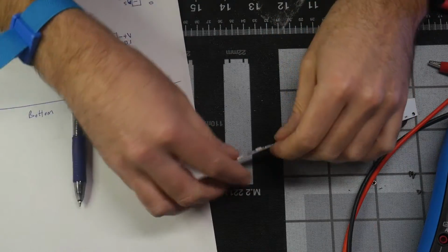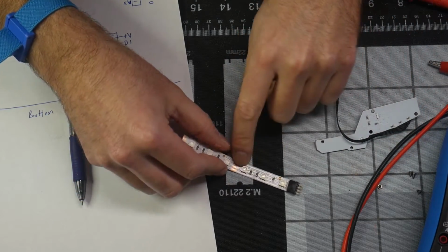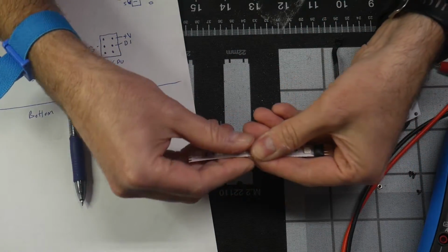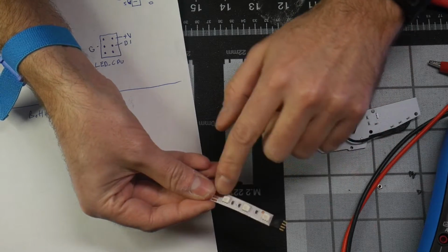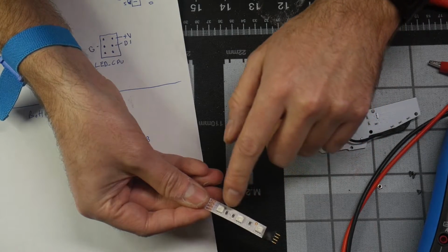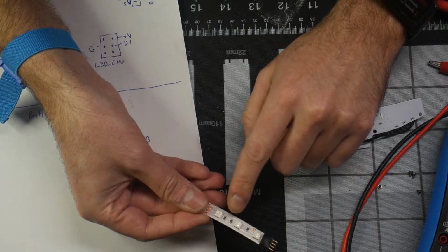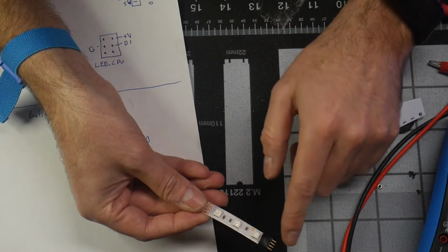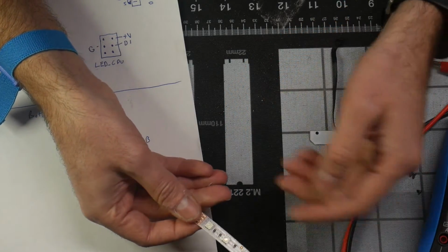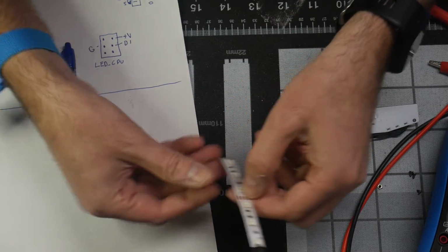Right here we have a strip, and as I showed in my other video, we have 3 LEDs in series. This strip right here and this strip are wired in parallel, but all the LEDs on each portion are in series. Sorry, we have one resistor for each of the colors RGB, and that's a current limiting resistor. Depending on the supply voltage and how many LEDs we have wired in series, it's there to prevent the LEDs from eating too much current and blowing up.